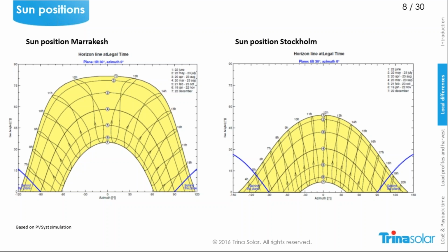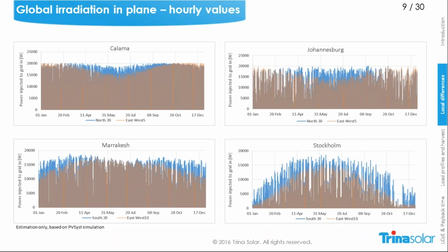Later we'll see what it means for the energy collection, and we will also go through examples, for example the module rotation, and what the differences are. Here is a printout from PVSyst showing when the energy gets harvested. That means it's an hourly plot.